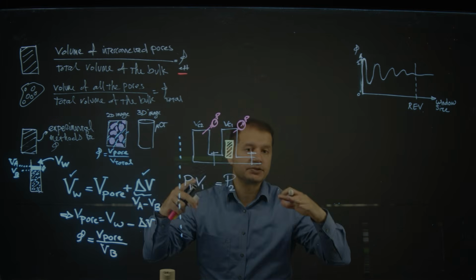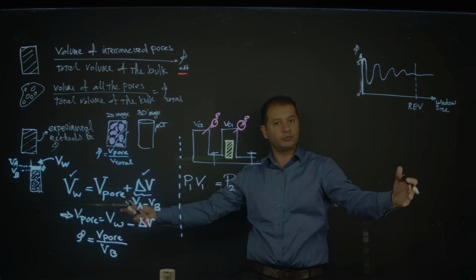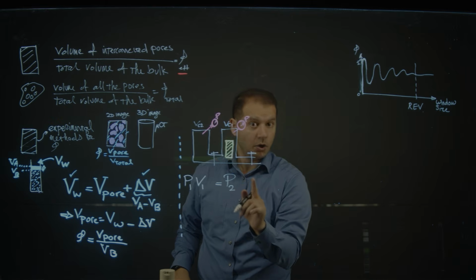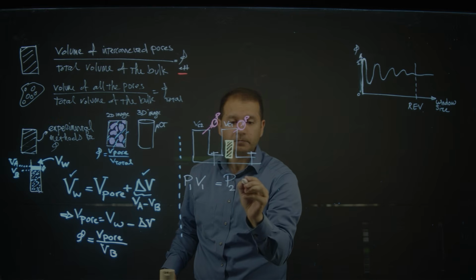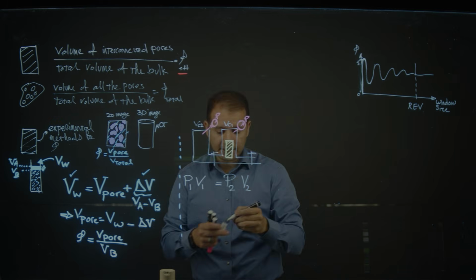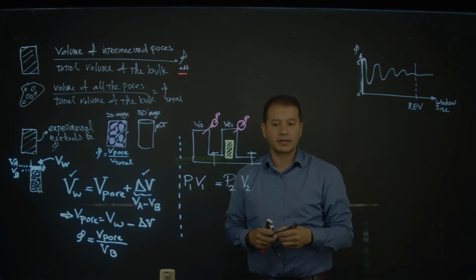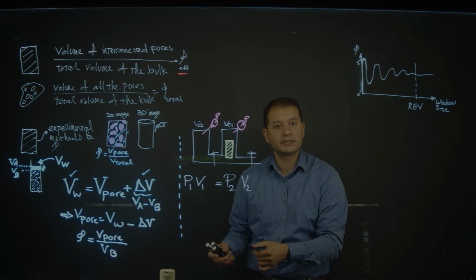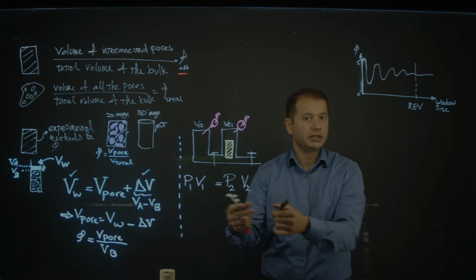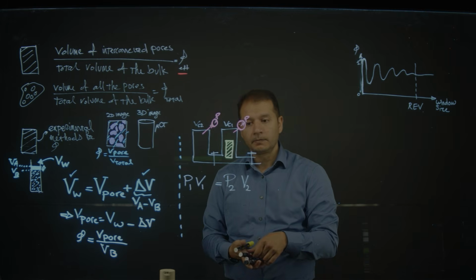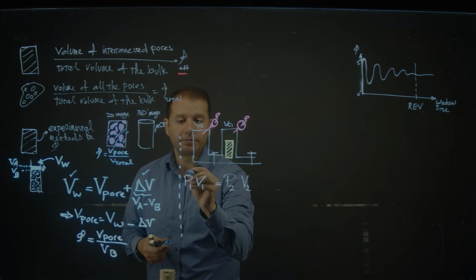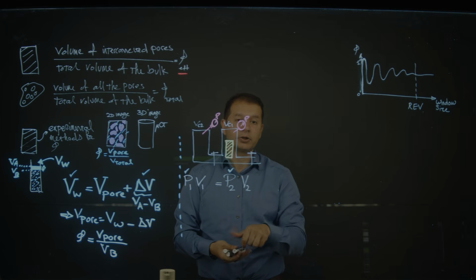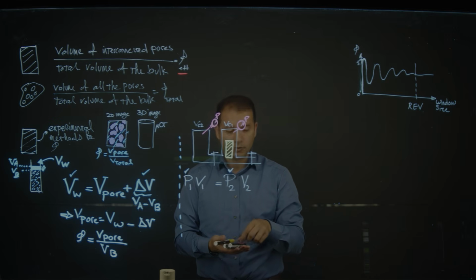The pressure drops naturally because gas is now expanding itself to fill up the other spaces, and I'm keeping the temperature constant. So P2 is known because the gauge gives me the pressure, and then the volume of the second stage of the gas will be the second volume. PV is constant due to the gas law when I keep temperature constant and assume that the system follows nearly ideal gas. So, what will happen? I can measure P1 and P2 from the gauges, but what are V1 and V2, volume 1 and 2?